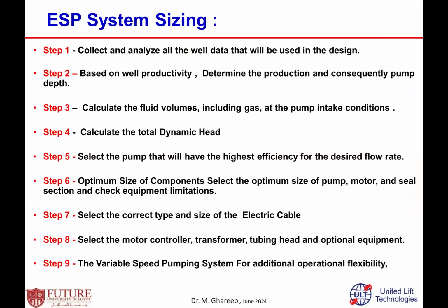However, on the website there is a very simple technique called the 9 steps technique. If you want to understand the basic calculation and basic design of the ESP system, you can go through this one, showing what you need to do in step 1, step 2, step 3, 4, and 5, like collecting and analyzing the data and predicting what will happen to the well: specific gravity, water cut increase, gas, fluid level even, because now I'm calculating based on a dynamic fluid level, but what type of reservoir is it?